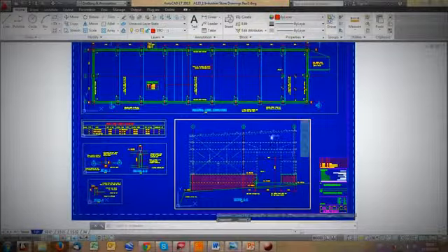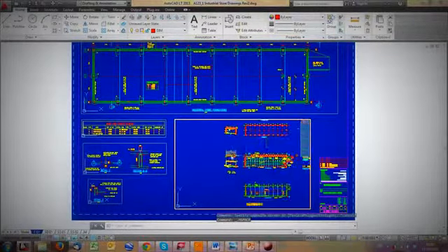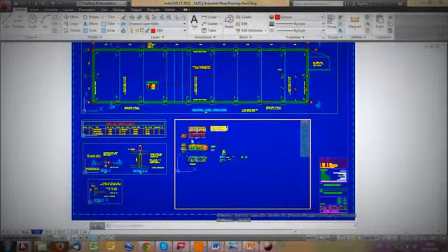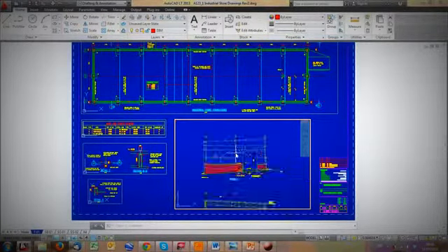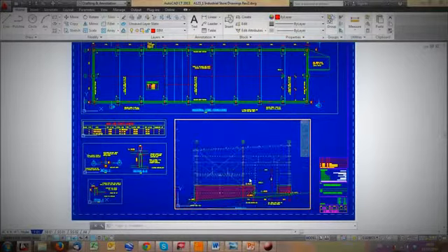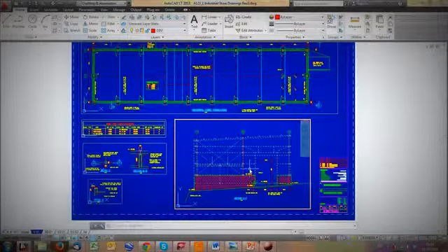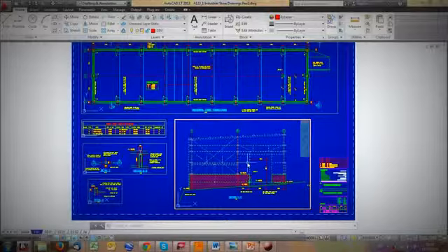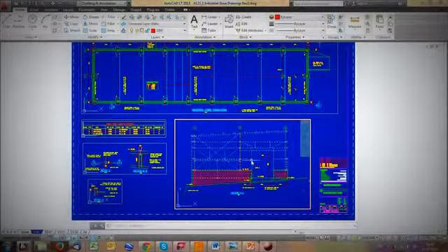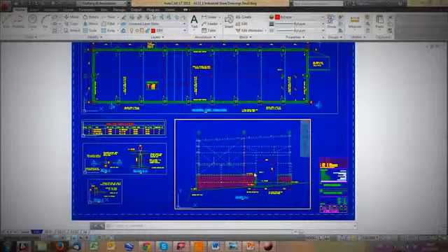So if I double click within this window, you'll see the line around the outside of my viewport goes thick. I can now zoom in and out and make my window focus on whatever I want within this space. And I zoom in now. If I want to create a specific view, a specific scale, and I'm going to do this again because everyone always confuses this, I'll do this in the future lessons. If I zoom in, I want to create a 1 in 50 scale now. I zoom out, zoom in, I get roughly the section where I want it to be.